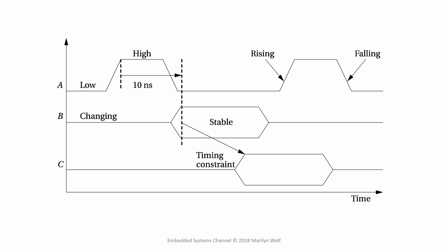We use timing diagrams to describe buses and other types of logic. A stable signal is drawn as a pair of lines, low and high. We don't know whether the particular signal is low or high in this case. That depends upon the situation and the particular data. But we know that whatever value it has, that value is a stable, valid logic value. A changing signal that is not stable is represented by a line through the middle.